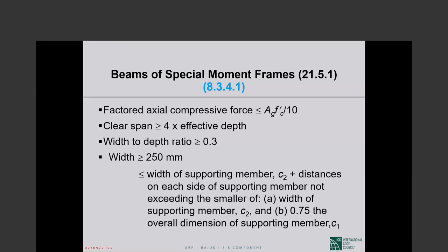Okay, the second question is much easier. When I said repeatedly that flat plate column frames are not allowed in seismic design category D buildings, I always say it as part of the seismic force resisting system. They cannot be part of the seismic force resisting system. That does not mean they cannot be used in design category D buildings.